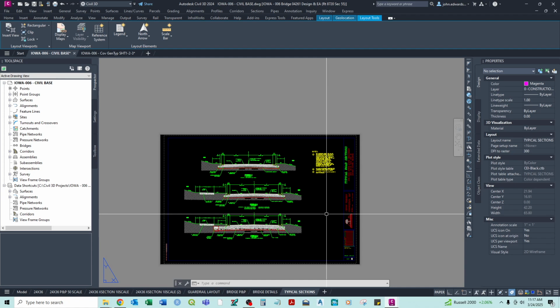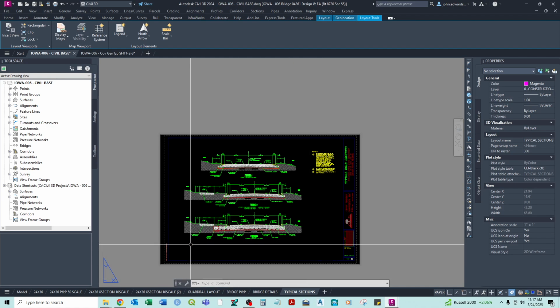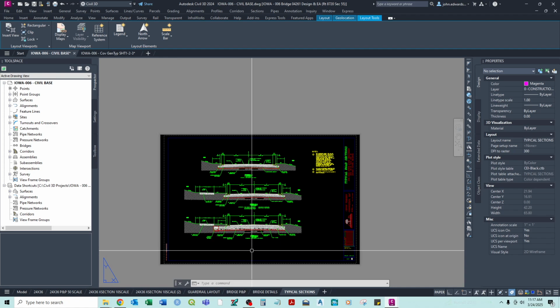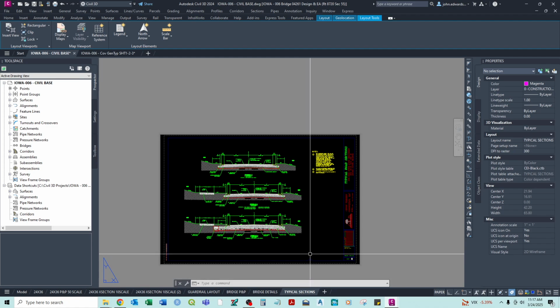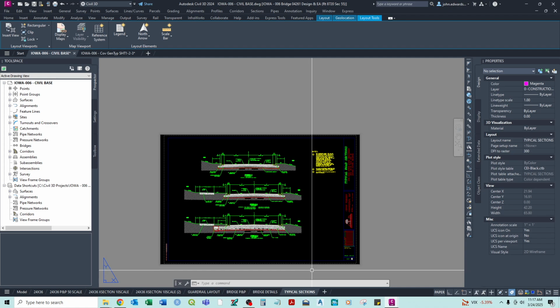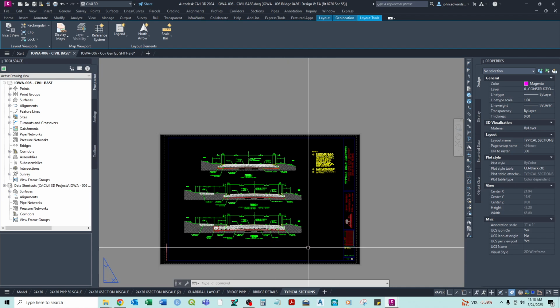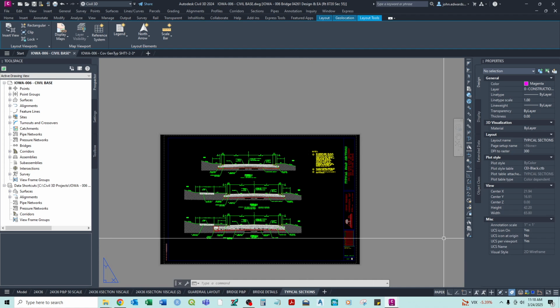The nice thing about that is not having to replicate things from other drawings. Obviously you can also always copy the whole drawing and reference that, but that's a good way to bring in a single layout one at a time. Now sometimes, depending on the drawing it comes from, it will again have a lot of unreconciled layers that you need to deal with, but that's fine. You can deal with that. So that's a quick overview of plotting and doing sheet sets and working with some of the layout views. So that's it for this video. Thanks.